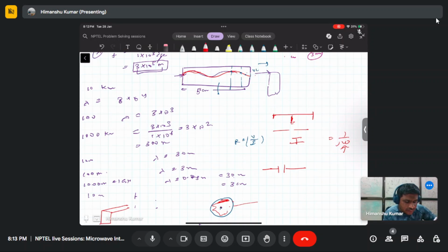The effect of this periodic variation you can model by adding the distributed resistance, capacitance, and inductance value in the transmission line. So the fundamental thing is this variation of the voltage along the line.